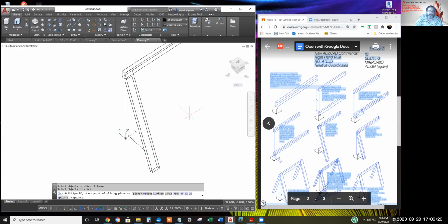Or typing anything, anything, 0 would specify a point on the XY plane, 0, 0, 0, its default. That alone would work. That is a point on the Z = 0 plane. Taking advantage of our chalk line, though, I'll click on the chalk line we drew on the floor, the Z = 0 plane. Enter for both. There's our cut.